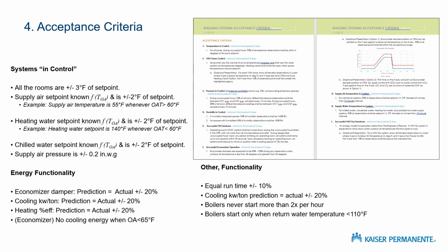This is the single most important thing that an HVAC design engineer can do to facilitate commissioning: to place a set of objective and measurable criteria on the expected system performance into the specs and into everybody's contracts. That removes all opinion from the commissioning period, which is insanely valuable and very necessary.